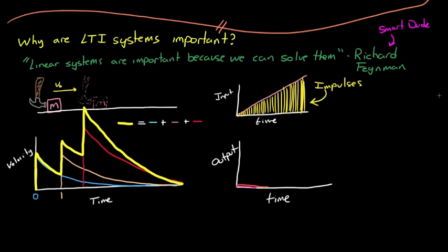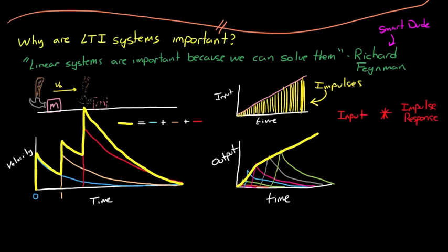Now, for the sake of this lecture, I drew these impulses very discretely. In practice, each of these impulses would be infinitely close to each other, and the height would be infinitesimally small. So when you added it up, you would have the time response of the system. And when you do this summation in the time domain, this is called convolution, which can be a very difficult integration.